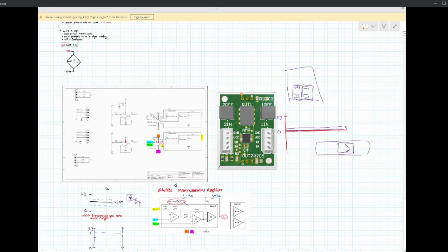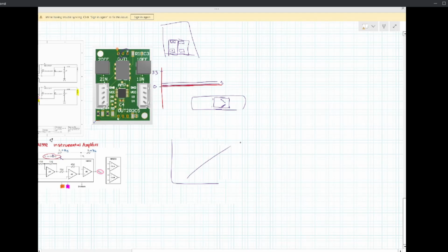Or you can just straight up connect your amplifier board through this port to an oscilloscope and apply different loads to your member and actually see what voltage output it gives you. Plot that in Excel using the linear regression. You get a y equals mx plus b. And you input your m and your b into the data viewer, and there you go, you got your force, and you got your torque, and it's really cool.